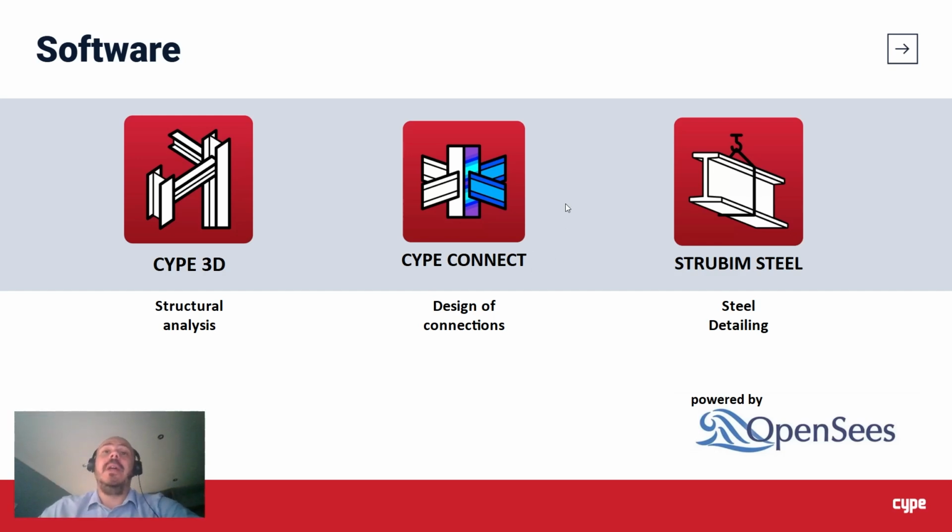In this software, the idea is to develop the model of the connection and analyze this model using the finite element method, then take the results from the finite element method and compare them with the limits that are available in different codes that can also be selected in the software, and then check whether these connections are safe or not.